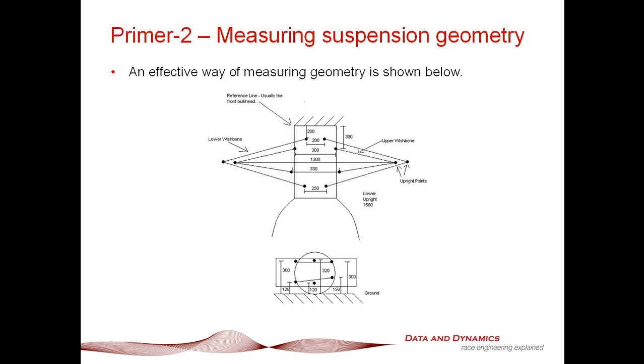You'll see here that for my upper and lower pickup points, I'm actually measuring across the pickup points. Now, I'm doing that for a reason. The reason I'm doing that is it basically minimizes error. But the great thing about it is that once you've got all those points to hand, putting them into your suspension geometry package then becomes absolute child's play. And indeed, what I'll often do is I will fill in this little template here, which is what I've done for a particular race car.